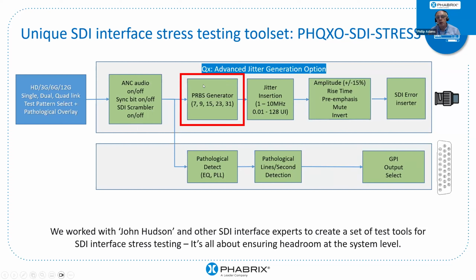We created a PRBS generator. That was through working with MACOM and Semtech. They do all the chip testing using PRBS initially. It's far more scientific and far quicker to get repeatable results. So we created a PRBS generator which replaces the SDI data, rather specialized, but allows you to use other pieces of kit.